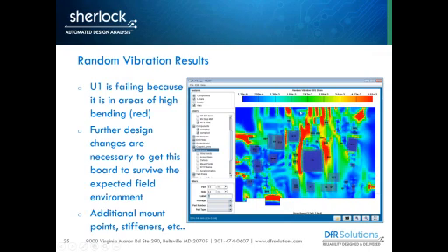Maybe the one thing that you'll usually see is what we call alleyways, or areas where parts are not overlapping, which allows the board to sort of hinge, and so all my bending is taken up in a specific location, or concentrated.